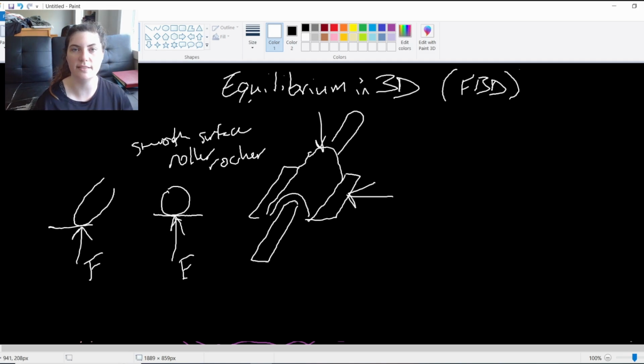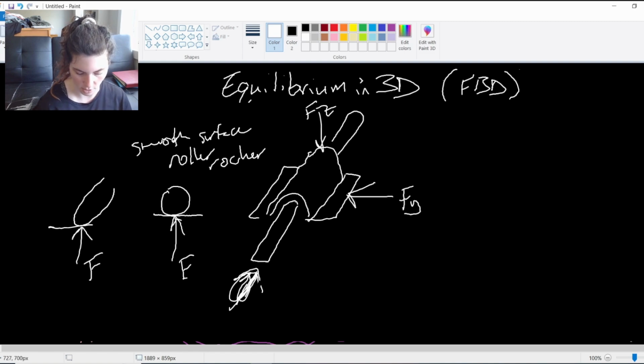It's whatever way this thing is oriented. So in this example, it could be like Fy and Fz, but it could still move in the way that this rod moves. So there's still a degree of freedom on this third side, but it works just like a pin where there are 2 support reactions that are just forces, no moment support reactions generally on these types of things.